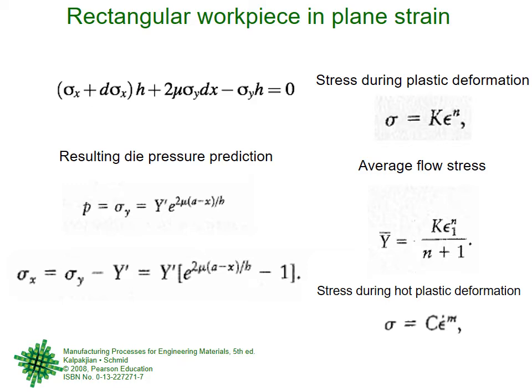The symbol capital Y. You see, when you have a stress, if you remember your tensile test and so on, a stress keeps on increasing until you get a value called yield stress, sigma y. Then it keeps on increasing again until you get a value called ultimate stress. Then it drops a little until finally it fractures and you get something called fracture stress. So the real stress is changing all the time. It is no fixed value. If it is exactly yielding, then it is sigma y. If it is exactly necking at the top, then it is ultimate strength.